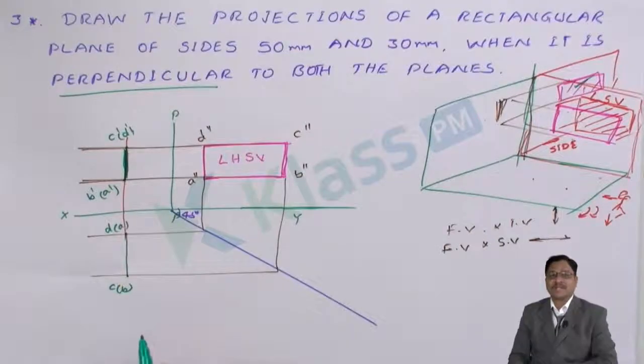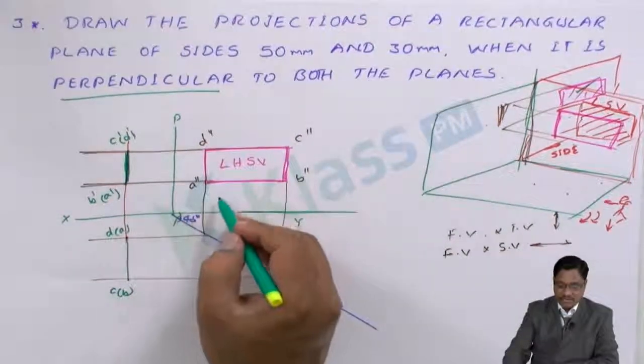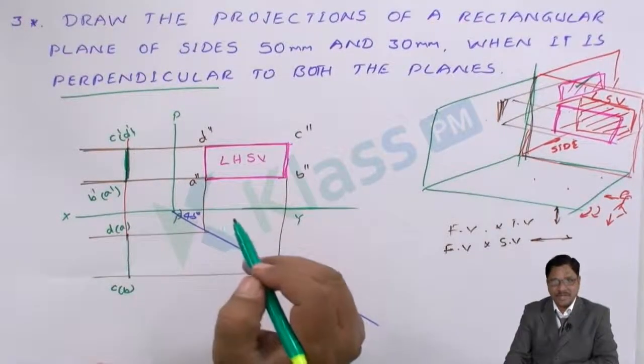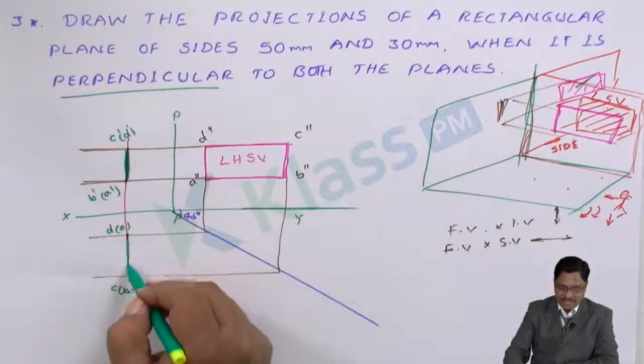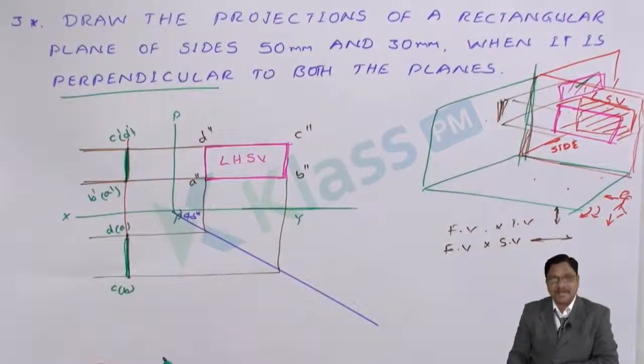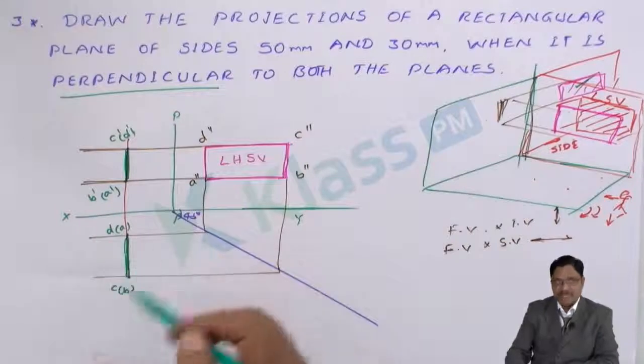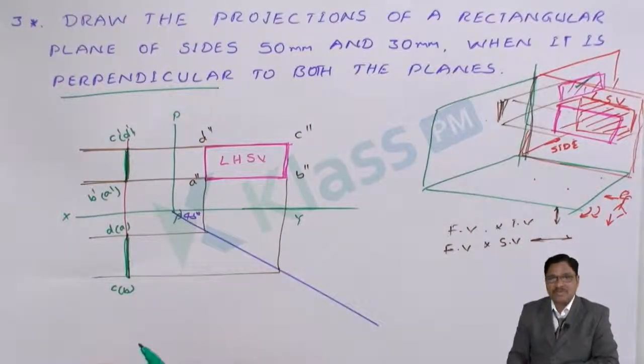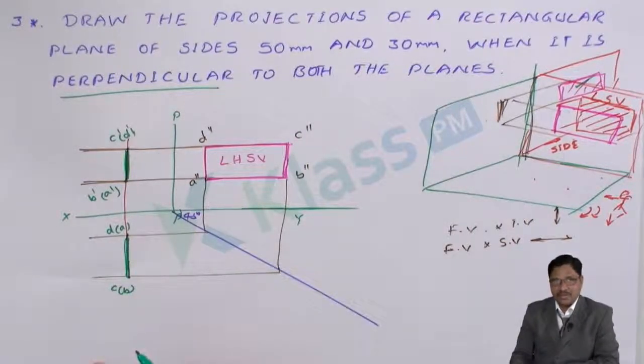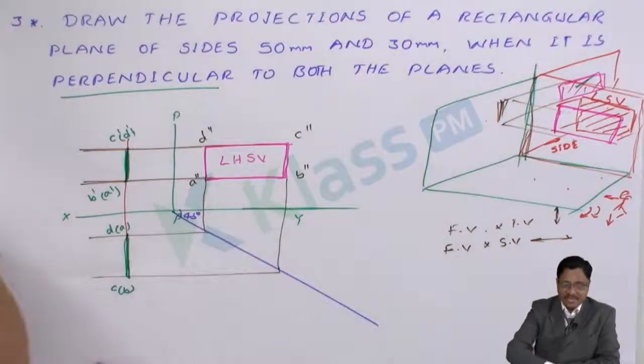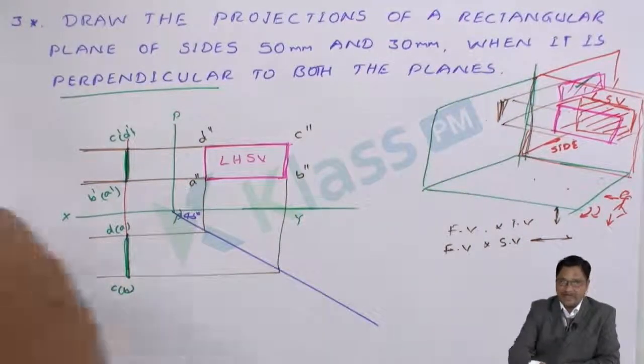Clear? The usage of pencil is very important, so that you can highlight whatever solution you get. The side view to be drawn should be HB, clearly. Next, the front view and top view should also be drawn HB. The remaining lines, whatever were projected to get the views, should be drawn very light using the 2H pencil. Once you have completed, you can finish the solution by adding the dimensions.